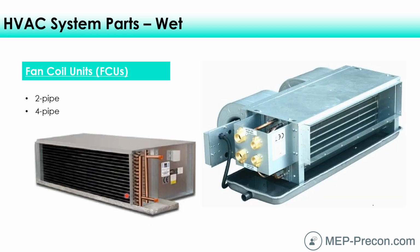So where does that chilled water go? Back to the chiller. So we make chilled water through the efficient use of the refrigeration cycle, and then that chilled water is going to be used. We have a pump. We're going to pump that water to these fan coil units. And a fan coil unit, unlike an air handling unit like you saw before, is a real dumbed down version of an air handling unit. A fan coil unit consists of a fan, as you can see back here, and a coil.